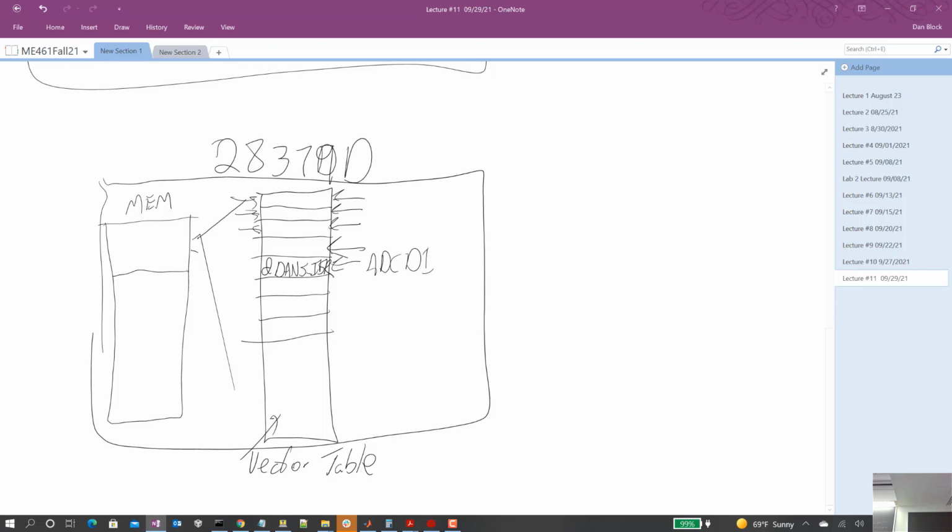So you're going along. The main place we'll be when we get interrupted is that while loop, printing the terminal, right? So we're sitting there spinning in the while loop, and 1 millisecond's gone by. So boom, you get the interrupt. Well, actually 1 millisecond's gone by, so you go tell the ADC to start converting. When those two conversions are done, then an interrupt's generated, right? That's actually what happens. And so at that moment in time, that's why we call it a hardware interrupt. In hardware, the CPU knows to go and look at this immediately. Okay? It knows to change.